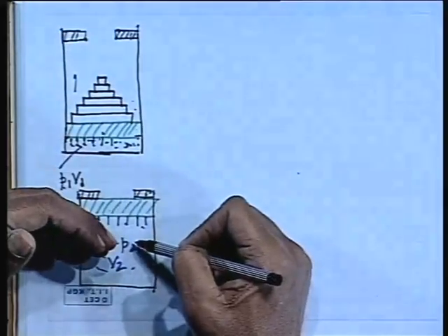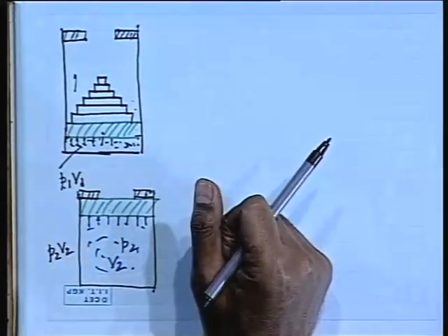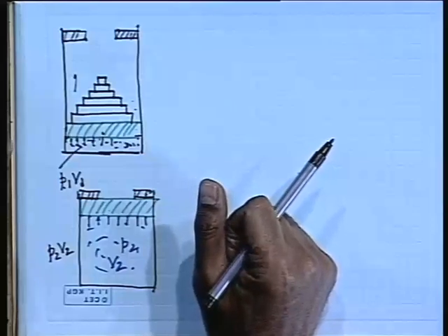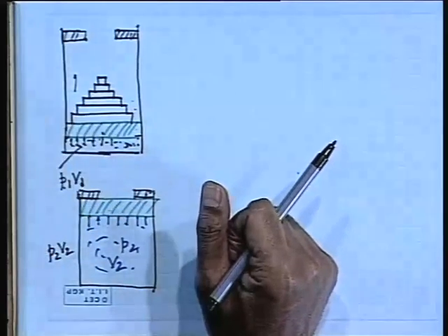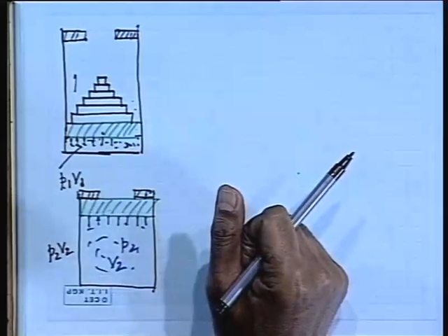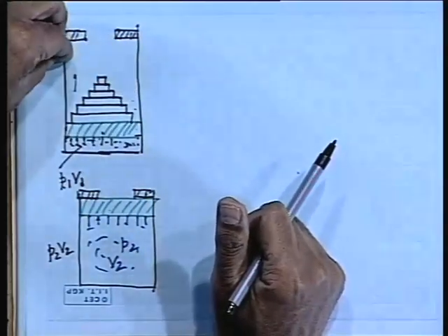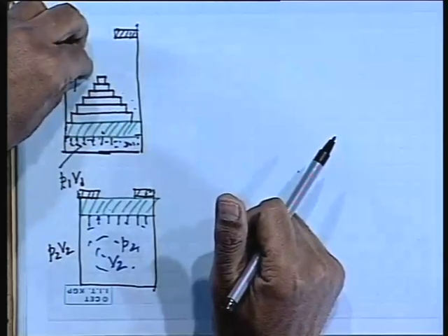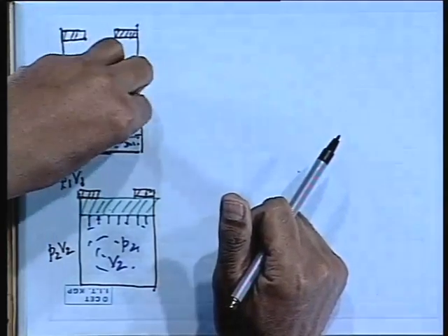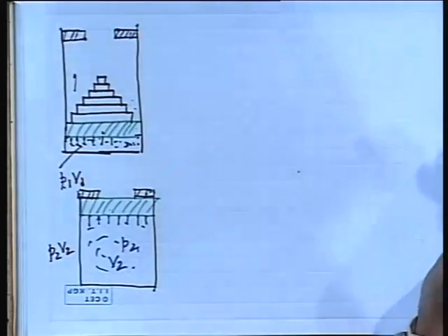Any intermediate state, if you want to observe by any instrument measuring pressure, temperature, other things, you will see they are not only varying with time, they may not be uniform throughout. So it is a very fast process, because we want to make it very fast. Obviously we keep a force balance imbalance, a high imbalance in the pressure, remove all the weights, and practically all natural processes are like that.